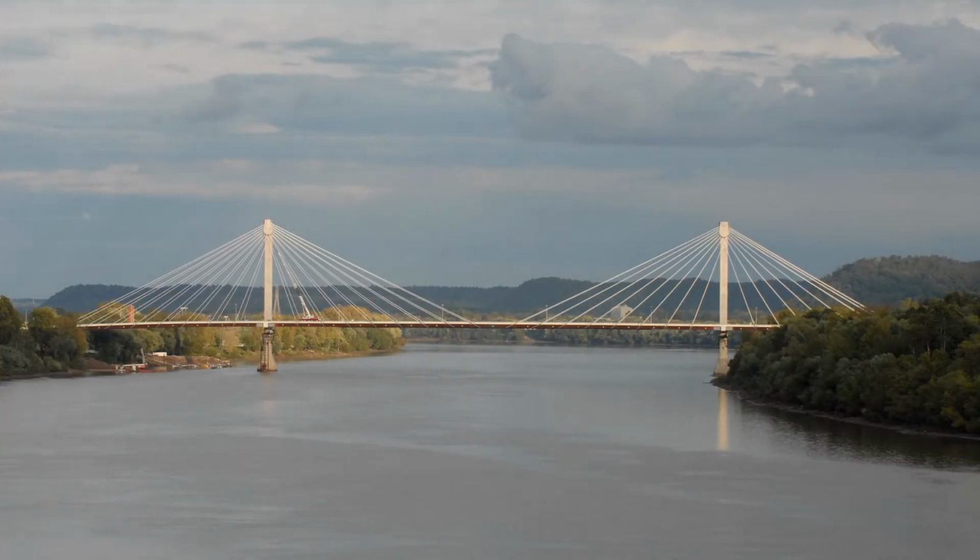Consider this bridge instead. This is a more modern cable stay bridge outside of Portsmouth, Ohio. And this is called the U.S. Grant Bridge. So with this cable stay bridge, it has a much more redundant system. So if you were to look at the distribution of the load path in this bridge, then a truckload here, the load goes up through this cable, down into this tower, and then into the foundation.